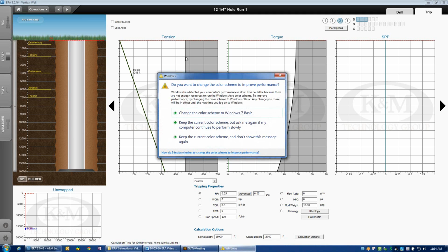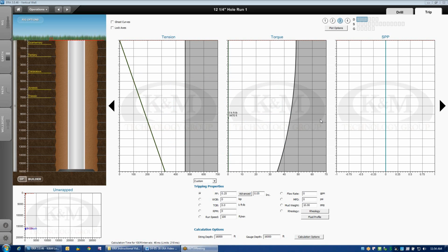of the pipe. Now we've assumed that we've got premium class drill pipe, and premium class drill pipe has a 12.5% reduction in nominal wall thickness in order to determine its tensile capacity, and then of course we overlay a design factor on top of that rating.